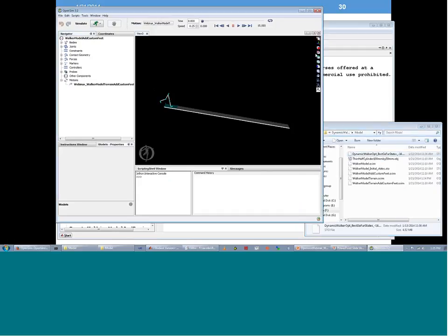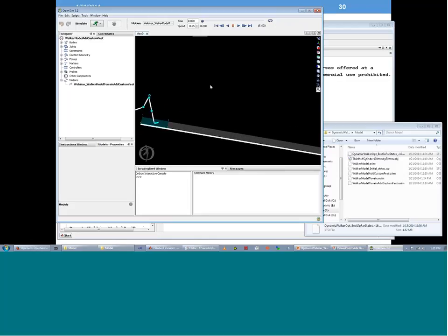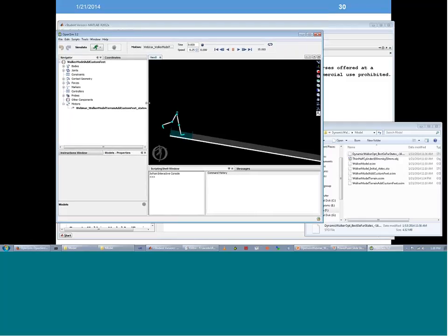And now on the right side of the view are a set of tools that control the various views. But there's also this very nice icon of a camera that's going to let us save a movie. So if I want to save a movie, I can control the speed, whether it's real time or half time, with these upper menus. I can change where I see in my movie by zooming and moving the screen around. This view window is essentially the frame that's going to get captured by the video. So if I shrink it, I'm going to get different sizes of my video.